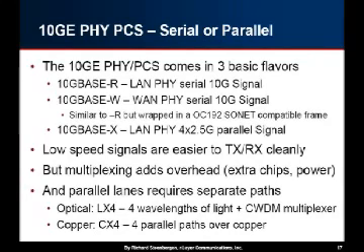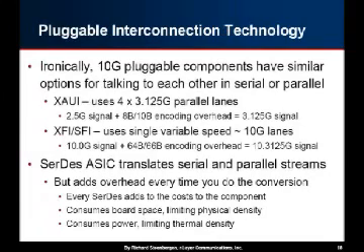There's basically 2 implementations of this. One for optical is LX4, which is 4 wavelengths of light, not standard CWDM, but roughly the same kind of spacing as a CWDM product. And there's a little mux built in, so it just transmits 4 different colors of light out the fiber, and it works great for sending 4 low-speed signals. And on copper, the variant of this right now is CX4, which is a proprietary cable or an InfiniBand cable, but it's 4 parallel paths over copper, so same concept.